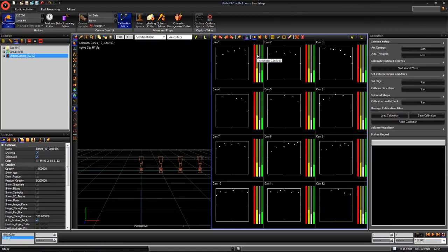Next is the threshold. This is the minimum value at which data is registered by the pixels on the camera sensor and considered for circle fitting. If you reduce the threshold value, the amount of data passing through the sensor is reduced. Gain is the next bar. You can imagine it as an amplifier. Increasing the gain will make the marker have less variance in intensity from the center to its edge.